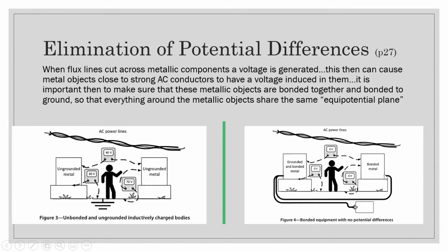There's continuity between the two. There is no voltage, no pressure relative to this point here and relative to ground. They are all connected, and so this person can walk around, they can touch anything, and they're not going to experience any sort of shocks. So it's really important to do that, especially around power lines.